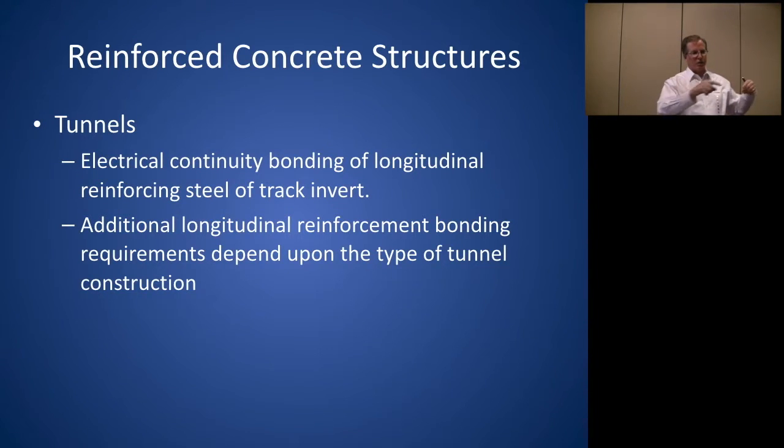If we didn't have it continuous, it would be jumping, like on those pipelines where it jumped across the joint, where you have resistance in those rebar laps. You would have a little corrosion there and it would end up popping at those laps. So that's why we weld those and we make it continuous. It gives it a big surface area for that current to transfer. And then we can also monitor it.